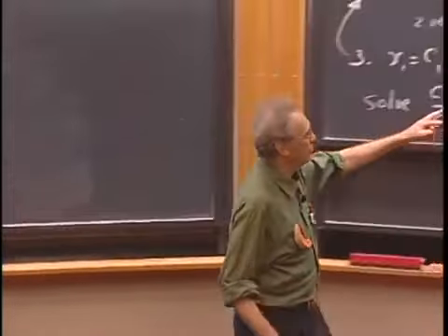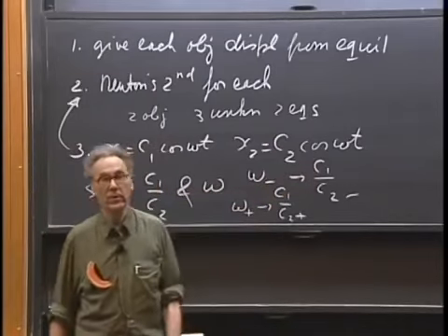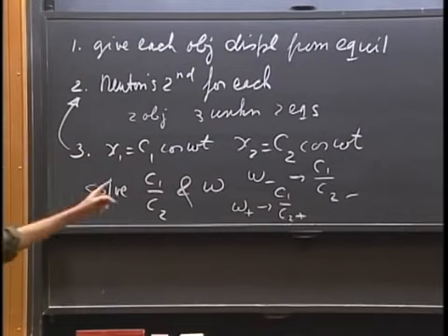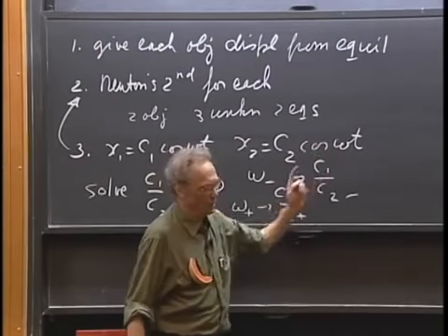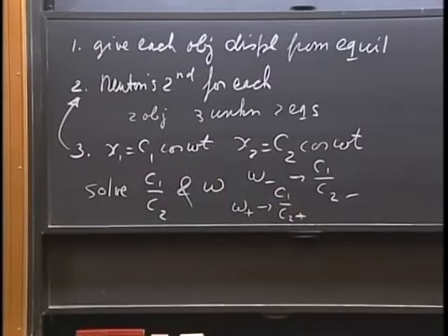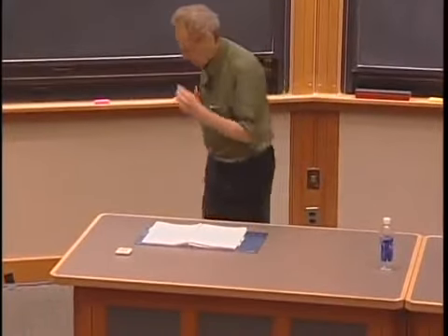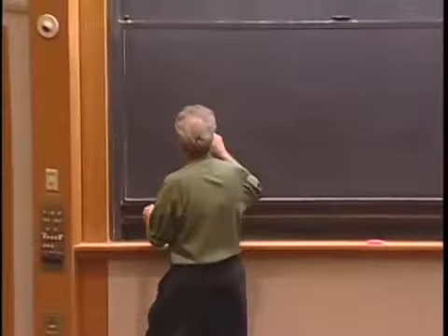However, they're in phase or out of phase. So the ratios can be negative or positive, but you never have any phase angles other than 180 degrees or 0, because we have no damping. We have taken the damping out. So it is essential that when you substitute that in Newton's second law, these omegas are the same, because they will then give you the normal modes.